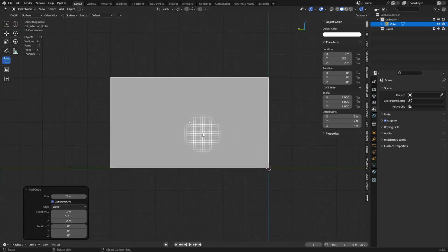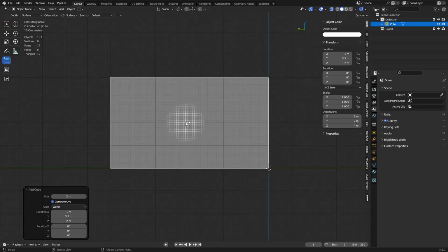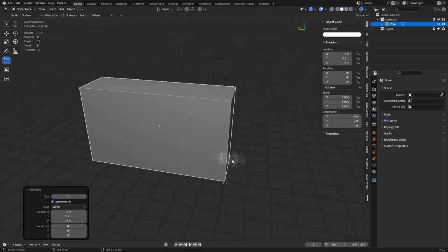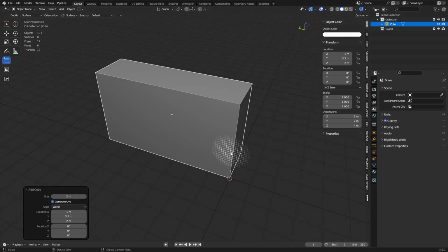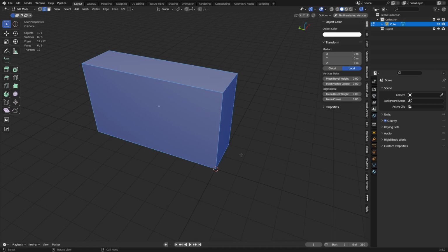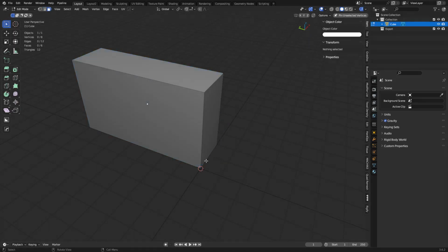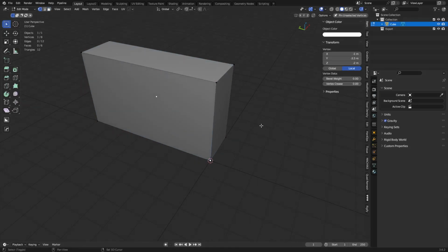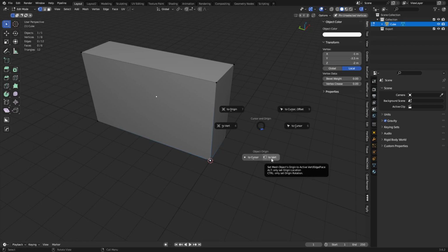But you can see that is now going to be at least on the grid in the vertical, but on the left to the right, it's still not in the right spot because we didn't go out to 8 meters, right? Not a huge ordeal. You can use these numbers if you wanted to, but probably the best way to do this is with the Machine Tools add-on. Once you get the Machine Tools add-on, you can select something like a vertex in edit mode, hit Shift S, use the cursor pie menu for the options in Machine Tools, and you can set it to a vertex and hold Alt while doing this.